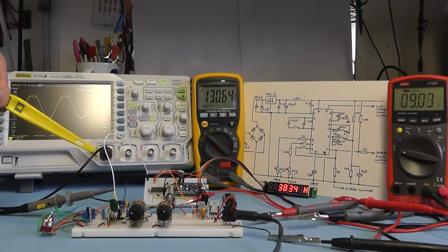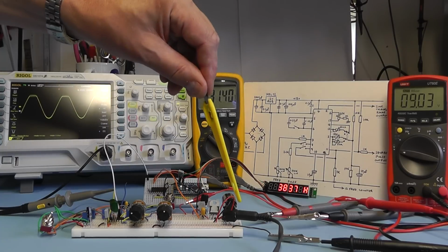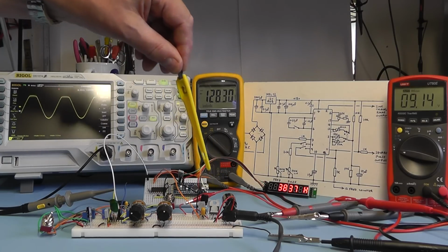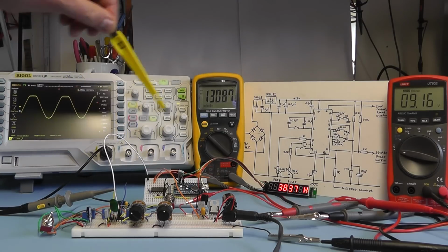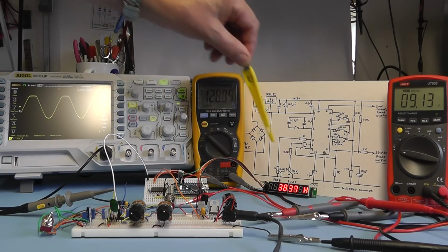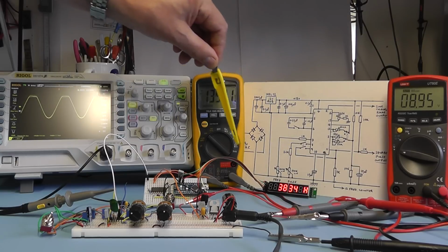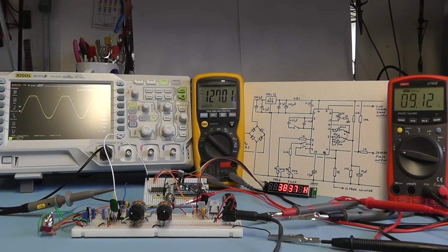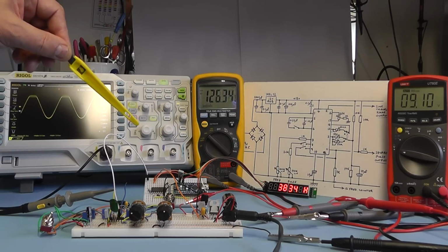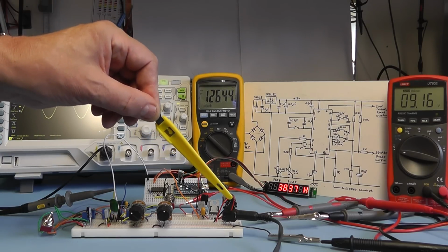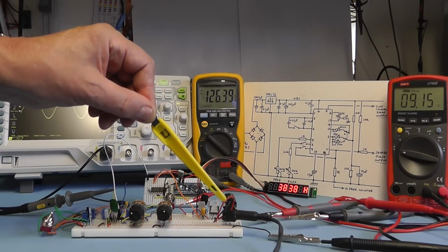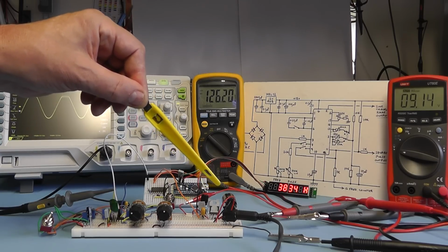So I suspect the problem is that the little mains adapter unit that we have to drive the 9 volts into this circuit is not sufficient to supply both the function generator and the current required for the display and the Arduino Nano. So what I will do is use a different AC supply to the unit here and just see whether we can resolve this problem.